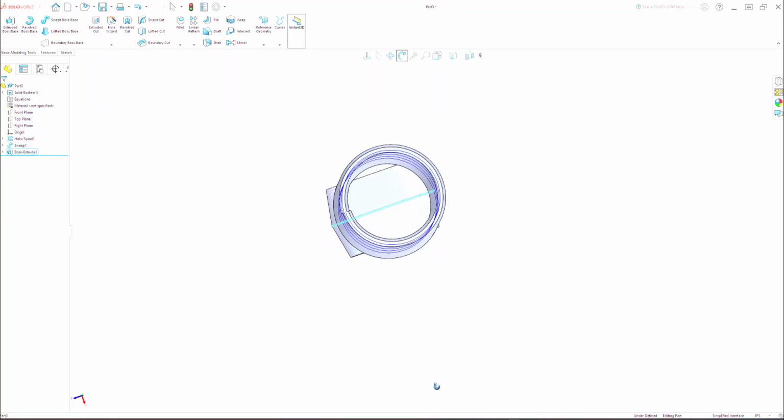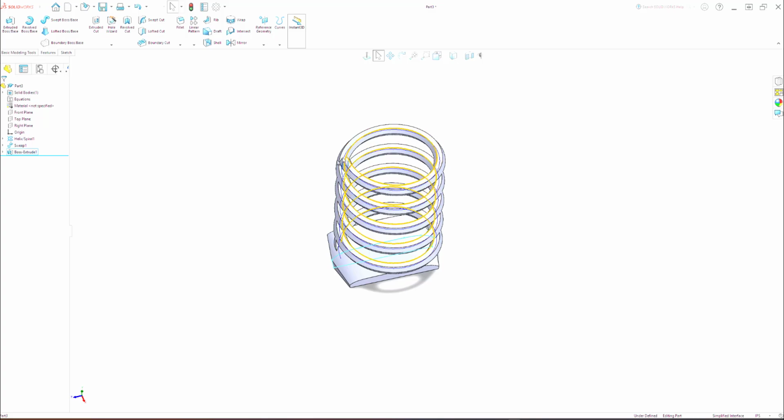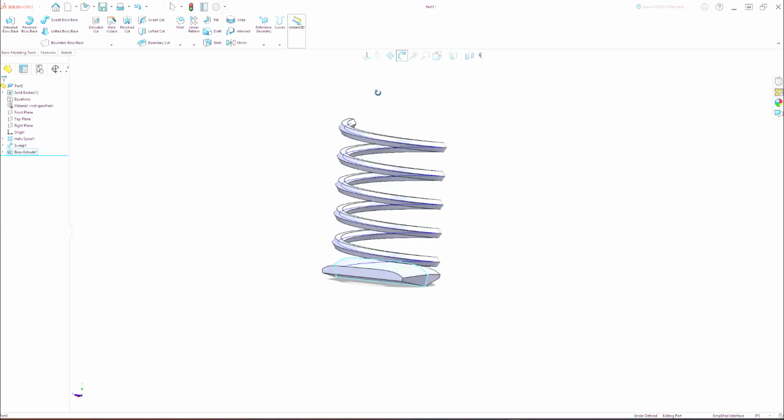To keep the coil stable, having a post in the middle and a hole on your top component will keep the coil stable. So the idea is that the coil will then compress and follow that post in the center. So that post in the center prevents the coil from moving right or left. You can make it move right or left. It adds another dimension to the flexibility.